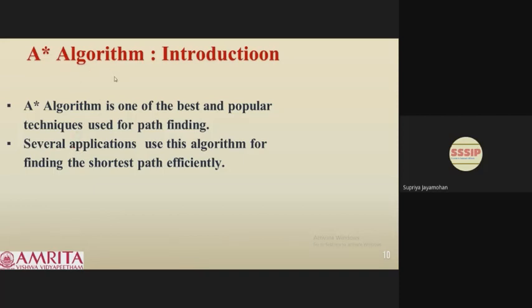In case you are going to start implementation, many of you are quite senior people who might have worked in various fields, in robotics, in all these algorithms. I'm talking about people who are new to robotics, who could easily start with A-star because it's a very simple algorithm, easy to understand, and it gives results in a quite efficient manner. And you would see that it is one of the algorithms that employs the best first search type of optimization, and as a result, it gives better results than the next algorithm that we may discuss, which is called Dijkstra.